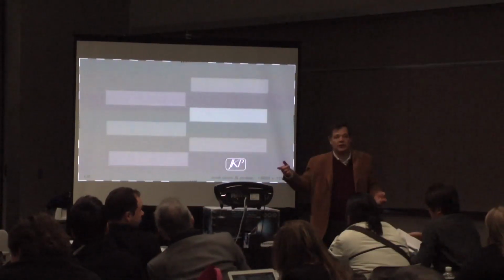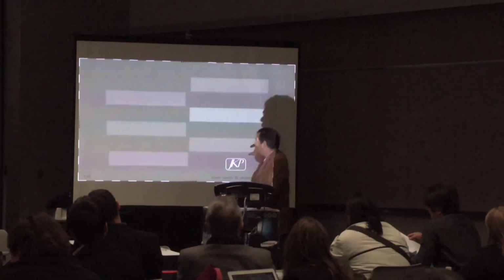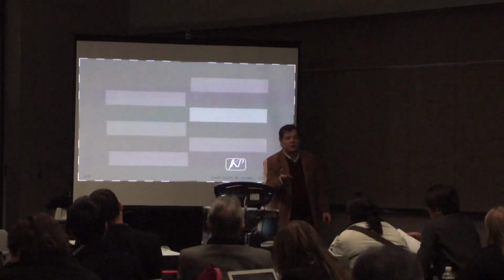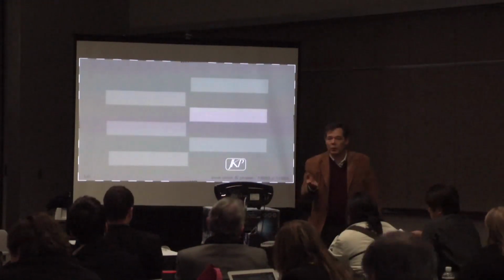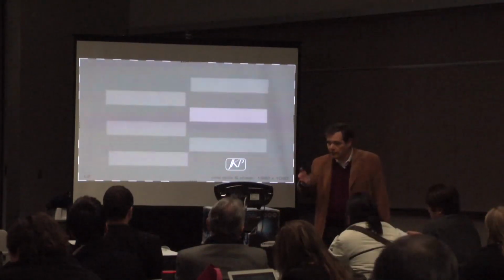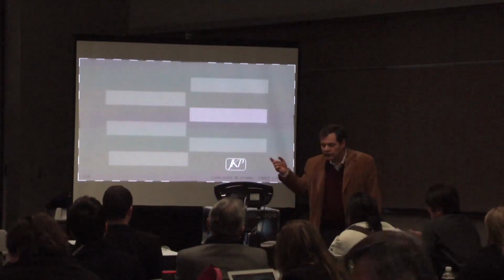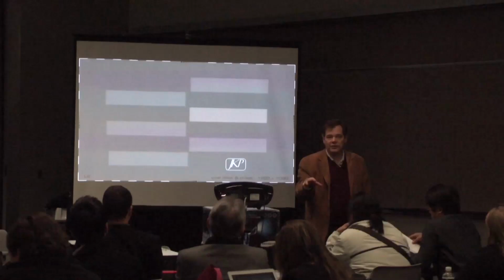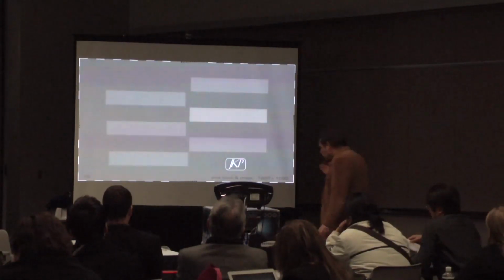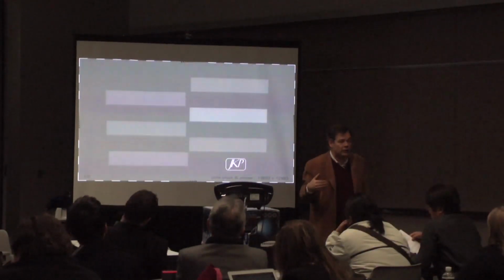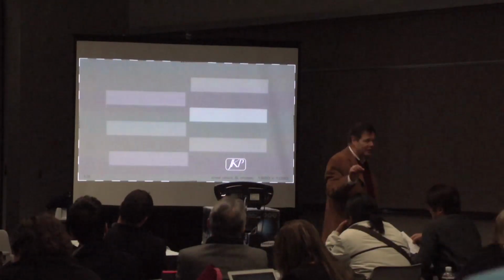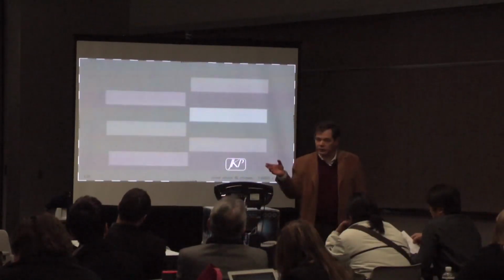Now, with this projector, to give you an idea, when I normally watch images with this projector, I sit at 2.5 picture heights away from the image. The SMPTE and ITU have agreed on 3 picture heights. And so viewing distance also becomes really critical to analyzing what's actually happening versus what you see happening.